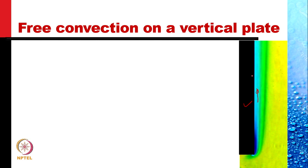The heat travels in that direction and this fluid is swept up in that direction, so that limits the region which is affected by heat. So this shows the extent of what is termed as a free convection boundary layer on a vertical plate.